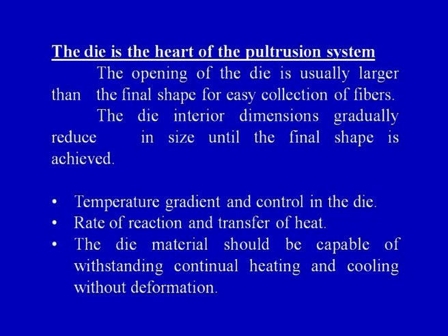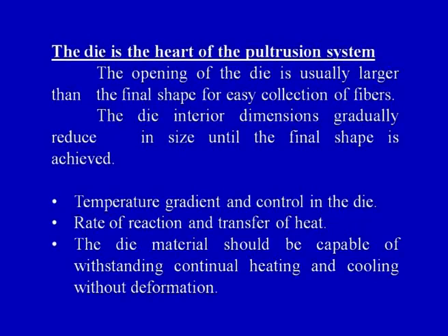The pultrusion die is the heart of the pultrusion system. So this is the most important part of the total pultrusion system, because the final formation of the composite product takes place inside the die only. So the opening of the die is usually larger than the final shape for easy collection of the fibers.